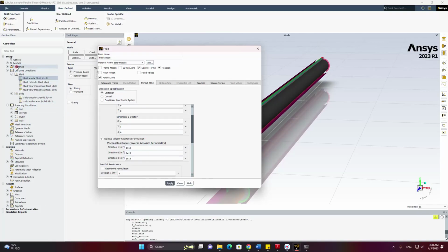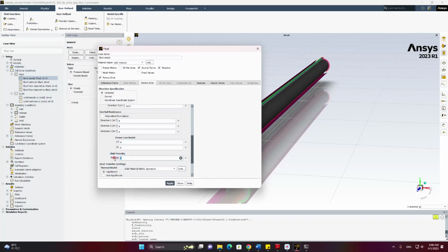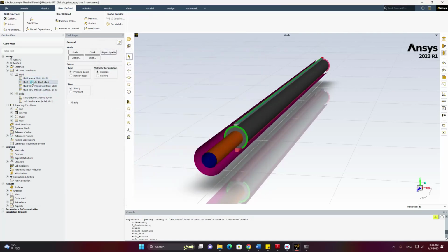Earlier we defined the material as a solid material, and now we should give the porosity. The porosity is 0.3 for the anode, and here we define it as the fluid anode default material. Now we are actually applying the previously defined material, which could have been any name. We apply that the zone named fluid anode is made up of this material. And we go to apply, close.